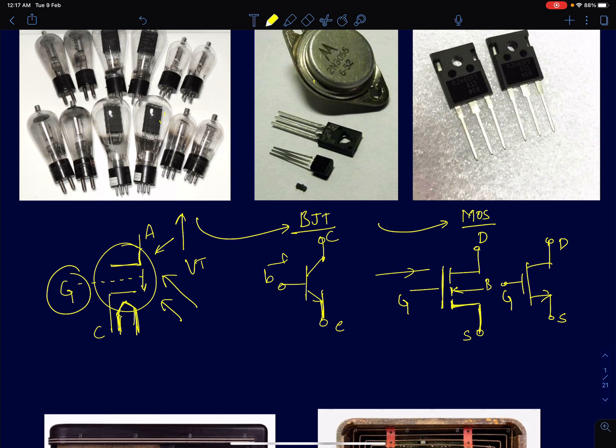If we can build a device wherein the flow of electrons between these 2 terminals can be controlled by application of voltage at the 3rd terminal, then we have an amplifier. Provided this amplifying device also satisfies the simple condition that the terminal at which we are driving the input should draw very little to no current, then we can attain huge power gain.